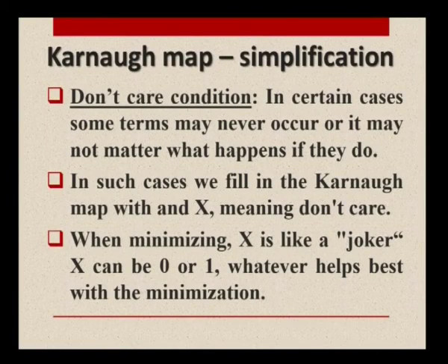Do you understand? 8 products, each product having 4 inputs, a very long expression, is getting reduced to a single variable input B here. So, this is the power of K-map. The only thing is we need to train ourselves in recognizing the quads, octets and pairs, etc. Now, how do we write the final expression? As I said, the largest possible groups are to be considered for writing the final expression.